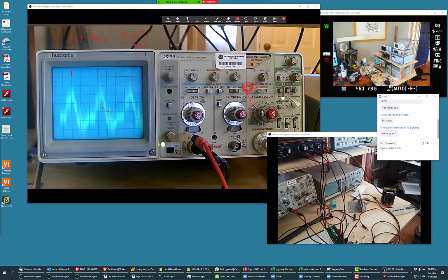we can start taking measurements by moving it around the screen to take advantage of the center lines, and then reading off, and then counting boxes, and then reading off the values per box from the dials. We'll get into the vertical part soon, because since this is noise, it's going to change all the time. We'll give it a sine wave, and then we'll see it better.